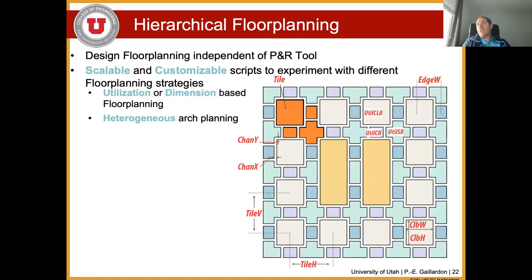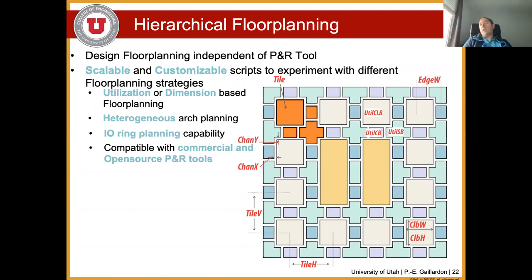And so one of the secrets is to use a hierarchical floor planning that enables scalable and customizable shapes inside of our block and allows for what I call a top-level Lego assembly. So you can guarantee that the timings of your fabric are well controlled, no matter what the size of your system is, and that the runtime is controlled to implement that.